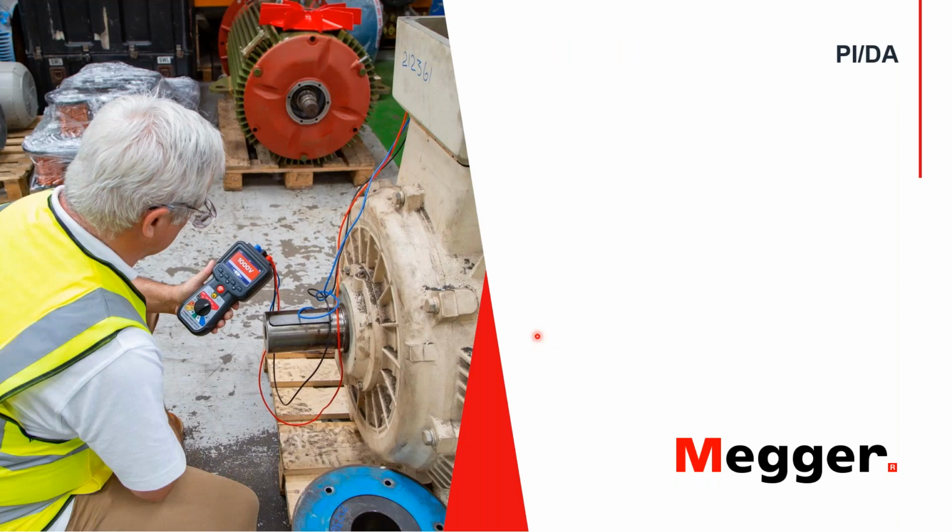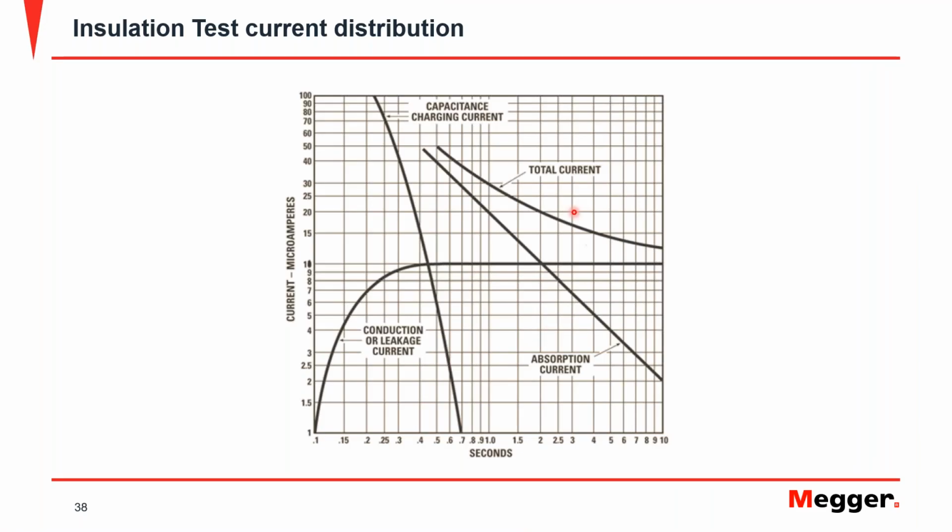Now, when it comes to polarization index and dielectric absorption ratio, what we are doing here is using the form of the total current, and we're using the fact that the total current should drop over time. As you can see here, it's high here, but then it drops over time, and it tends to get as close to the conduction or leakage current as possible.